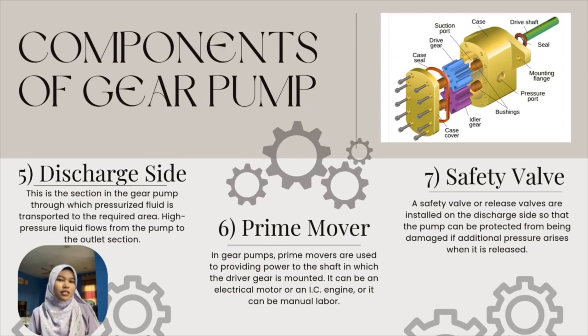And the last one is safety valve. The safety valve or release valve is installed on the discharge side of the pump. It is a critical component to protect the pump from damage in case of excessive pressure buildup. When the pressure exceeds the set limit, the safety valve releases the excess pressure to maintain safe operation.